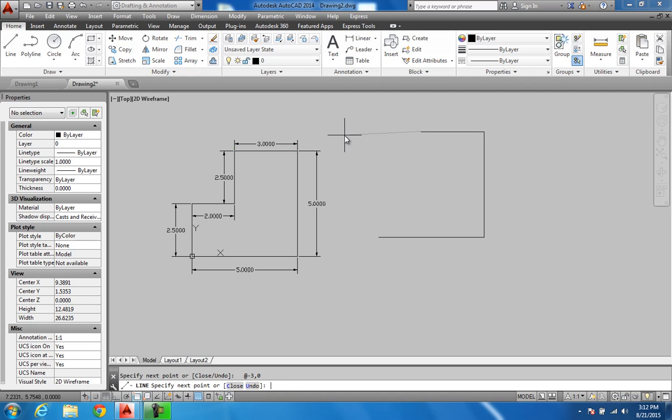And those are just temporary origins, guys. Your origin is always 0,0 going to be right here where we started this other drawing, but we can make them temporary. That can help us to draw when we're away from that origin and we don't know where it's at. So another thing is we're coming on down here to this point, so hit "at" again and hit x is 0, comma, we're coming downhill 2.5, so it'd be negative 2.5, enter.